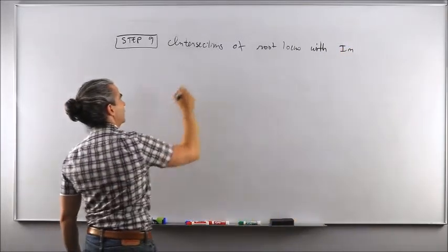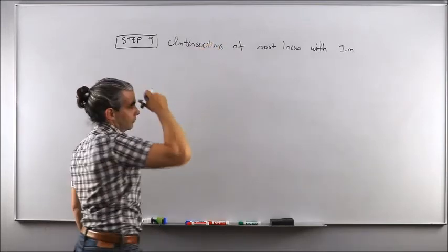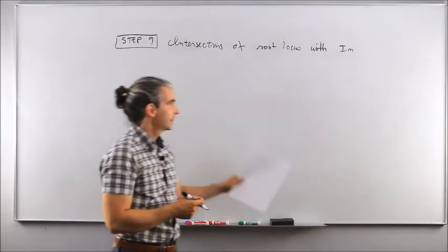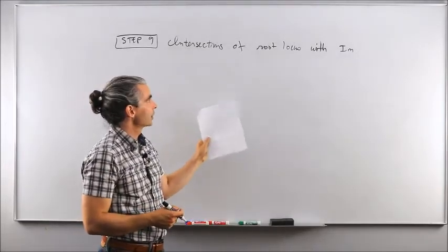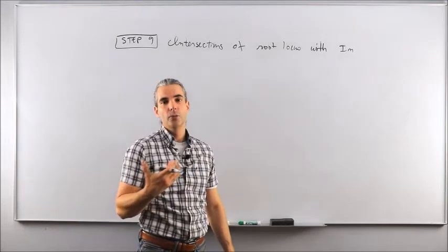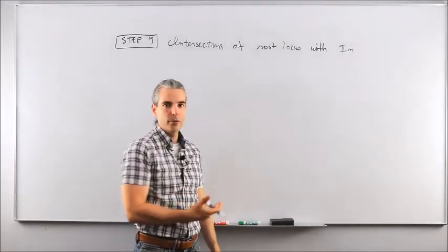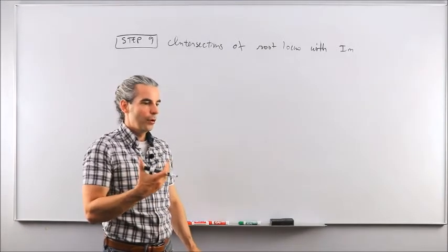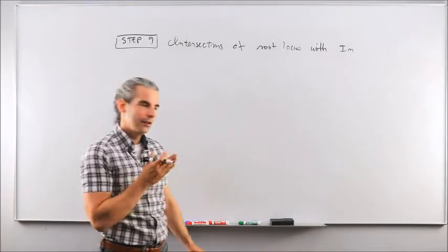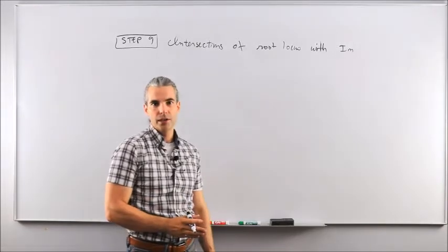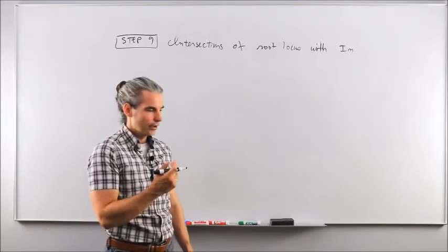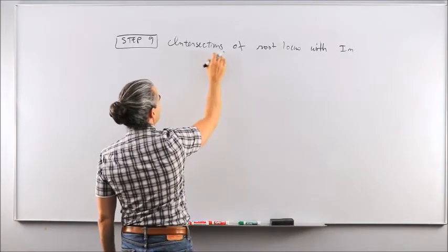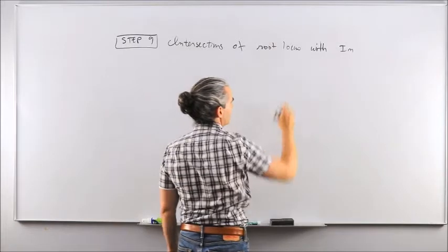Why is that an interesting thing to calculate? Well, to get a more accurate representation of the root locus, obviously, but also in this step, we should be able to figure out the value of the open loop gain, Kp in our example, or generically speaking, just K, that would make the poles transition from the left-hand side to the right-hand side of the complex plane, or vice versa, because they're going to move from right to left or left to right at these specific intersections of the root locus with the imaginary axis.